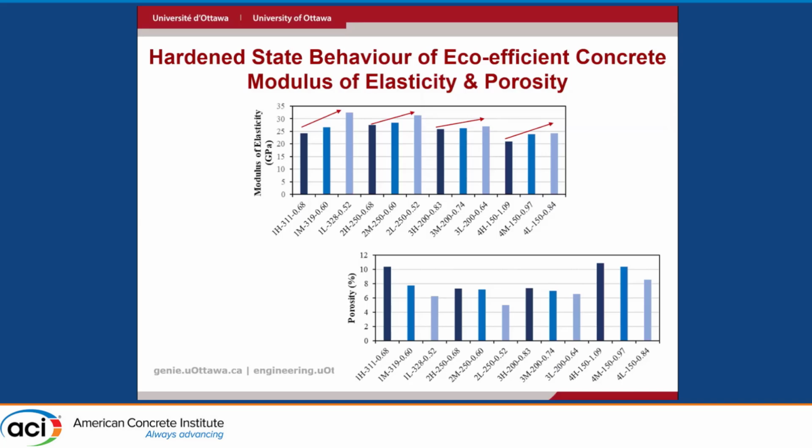In this case, we used limestone coarse aggregate and a natural sand. So we didn't play with different types of lithotypes of aggregates to try to get different values. We also tested the wet porosity, so capillary porosity via vacuum systems, and we could see that the ranges of our PPMs are between 8 and 6. This is definitely not the total porosity in the system because we didn't do any type of mercury intrusion and so on. This is the capillary porosity, the one that we can measure via drying and wetting under vacuum. But it looks like as we are reducing cement, our porosity, our microstructure is becoming better. So that's very, very good news.